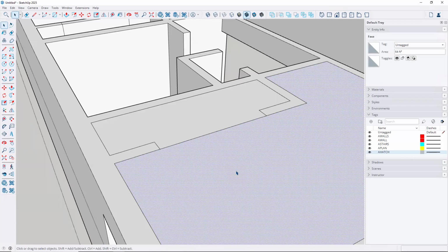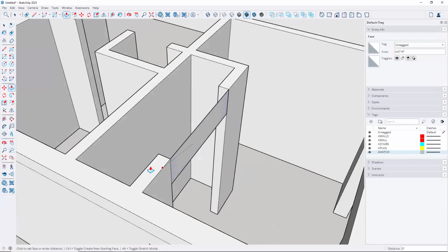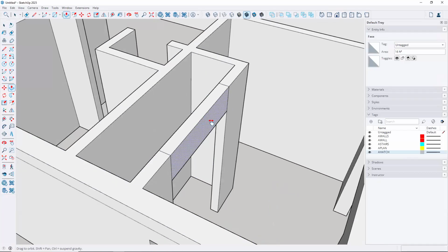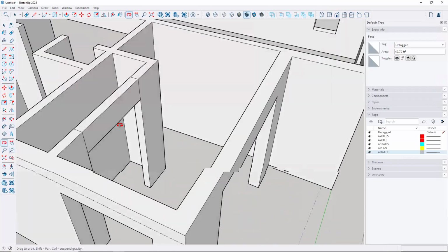Tap the space bar. Click on the surface, delete. Click on the surface, delete. That's just the nature of SketchUp. And now, P for push-pull. Pull this surface back and let it align to this midpoint, or any edge right there. Give that a click. Done. And that's how I can generate that opening.